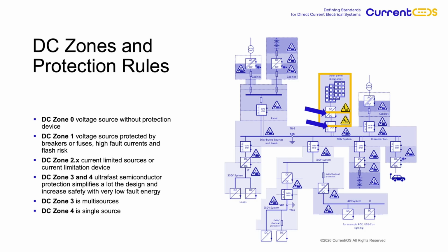In Zone 2.2, hybrid circuit breakers are introduced to further reduce capacitor discharge and incident energy during faults. However, designing and implementing these systems still requires highly skilled engineers. Mastering transient phenomena and overvoltage issues remains critical. Standards groups are actively addressing these challenges, but guidelines are not yet in place.